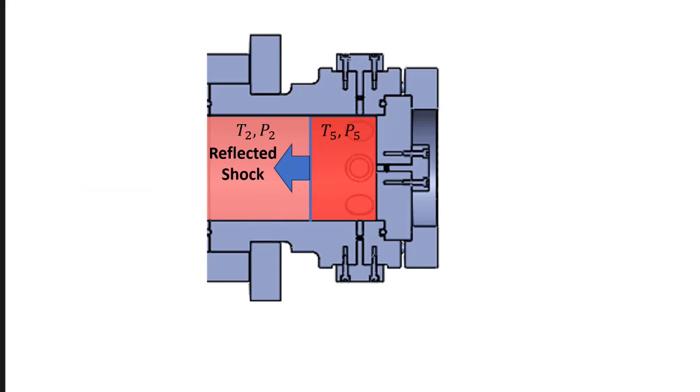The value of this is that this fuel-air mixture has been heated to a very high temperature, usually 1000 Kelvin to 2000 Kelvin, and heated so fast that it has not had a chance to react. But it will react within a matter of microseconds, and I need to know the temperature of this gas, called T5, before it does. There's no physical probe in the world that can record a temperature of thousands of Kelvin over the course of microseconds, but I can calculate the temperature from other measurable shock properties.